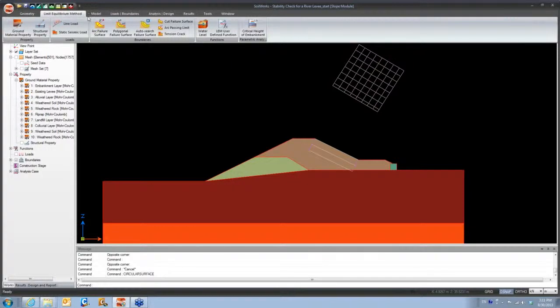So what are these straight lines in the right side? Oh, those are your arc tangents. There'll be a certain number of circular tangents along those lines. That's how you tell the program how many curves you want to model for your slip surfaces. Currently there are 3 white lines, which is the preset value. But if I wanted to create more slip surfaces for a more detailed analysis, I would create maybe 5 or 6 lines, and then the program would create more slip surfaces to analyze.